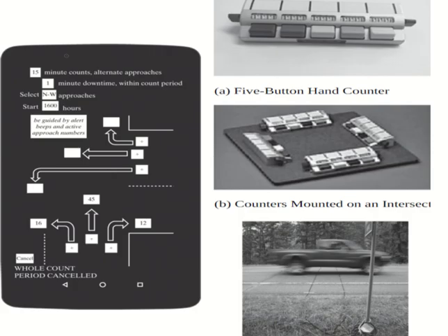No disturbance, nothing, no excavation needed, no difficult type of installation needed. You just peg them on the side of the road and you lay it out on the road itself. When the car passes, there's a sensor on the tube, and that sensor is connected to the counter on the side. So there's a counter installed on the side of the road, and the sensor is in the tube. When the car passes, the sensor will send the signal and the counter will count it.